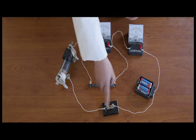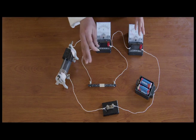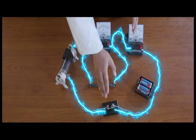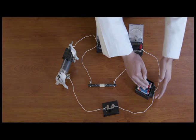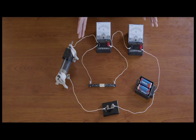So when I keep the key like this, we call this an open key. It is as good as keeping the circuit off, the switch off. But when I insert the key, this is a closed key and the circuit will be complete. And then from the other end of the key, it is connected to the negative terminal of the cell. Hence, this is the complete setup to verify Ohm's law. Now, let us take some readings to investigate the change in current and voltage and then verify Ohm's law.